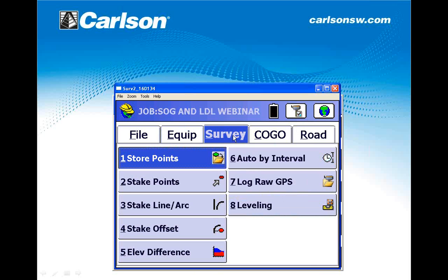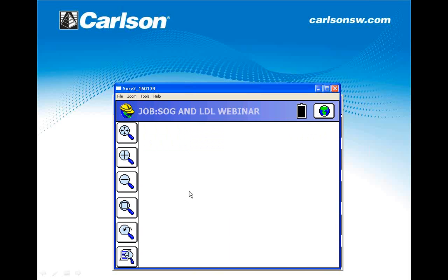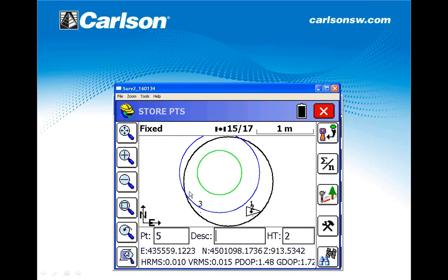Important is, of course, that we are setting a good antenna height, to make this tolerance work fine, because here we are getting real-time readings of the tilt sensor, so we are getting the bubble moving. The black circle here is, we could say, the viewer of the vial, it's fixed. The blue line is the bubble, as you understand the bubble in a physical vial, and the internal circle that is showing green right now is the tolerance vial.